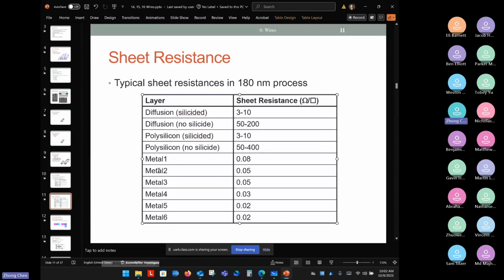You can start with metal one and then route it out with metal two, or even a top level metal, to get lower resistance, depending on the metal layer. But the metal is typically used for the interconnects between the drain and the source.